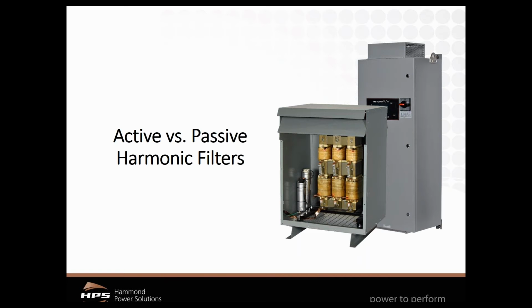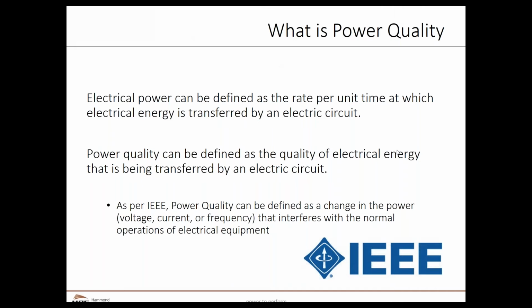Bob Ellis: Thank you, Mike. So just to start off the presentation, I wanted to get into what is power quality. Electric power quality is the degree to which voltage, frequency, and waveform of a power supply system conform to established specifications. Good power quality can be defined as a steady state voltage that stays within the prescribed range, steady AC frequency close to the rated value, and a smooth voltage curve waveform that resembles a sine wave.